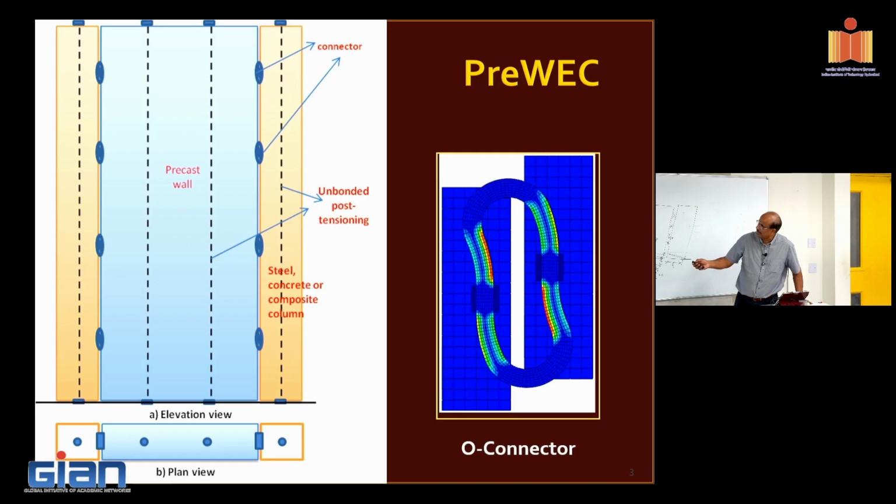at a different connector. So here's a wall panel, this is a column. This is a very cheap system, basically a laser cut O-shaped plate. You take a steel plate and just cut an O section, and you can dimension the O section to come up with the desired feature. You could see it's welded here, and then it just goes through the deformation.